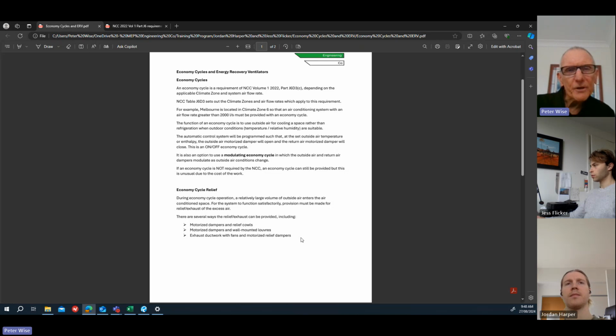So I started my career in Melbourne, and my first job was with consulting engineers, and we worked on big projects. And we would always have this debate about whether we should have an economy cycle or not. And if it's a large enough building, the answer would always be yes, because even 40 years ago, we were very conscious about energy consumption, and an economy cycle can provide very big savings by not running the refrigeration when you don't need to.